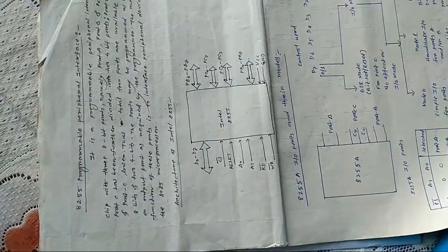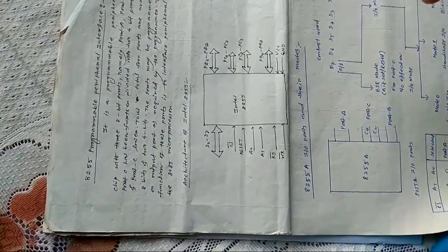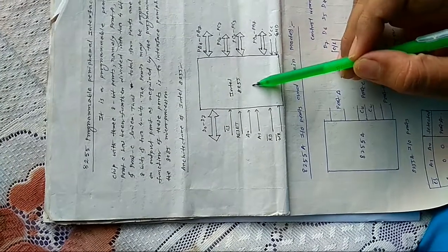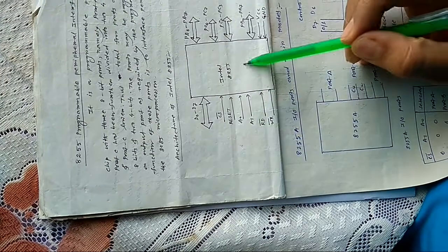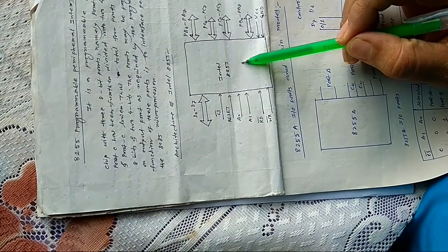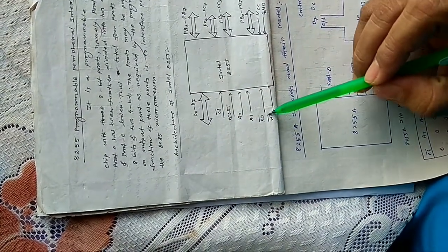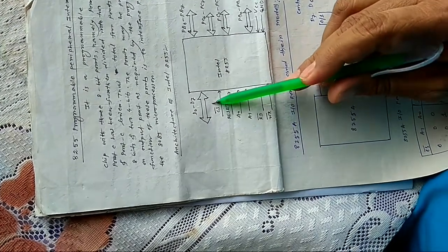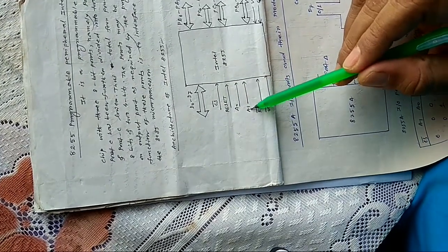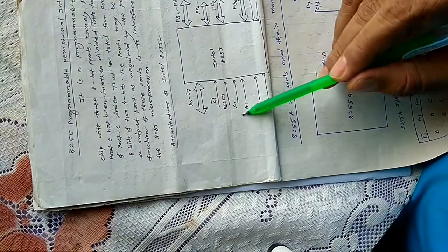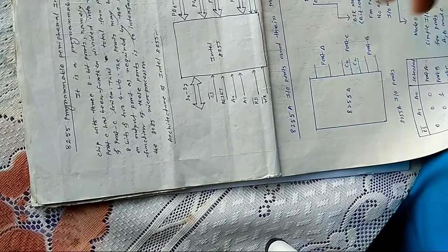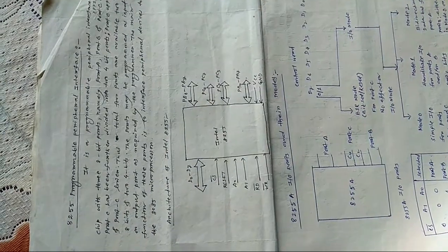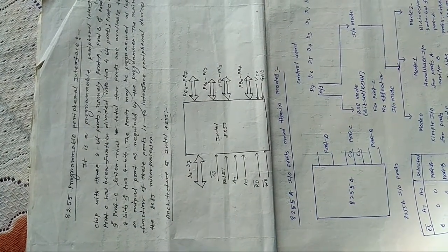Okay, and the processor will control these 8255 through which signals? This is the read bar signal, write bar signal, chip select bar, A0, A1. These are the address bus, A0 and A1. Okay, so read bar and write bar, all of you know the function of these signals. Both are active low signals.